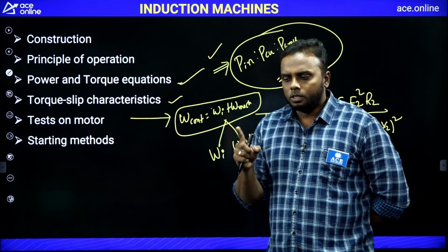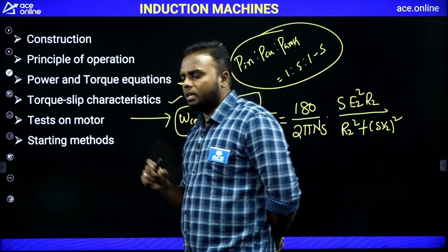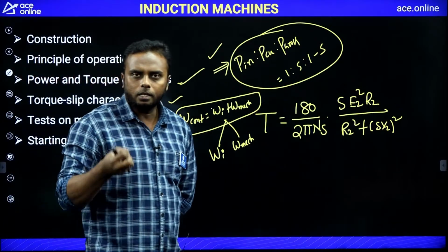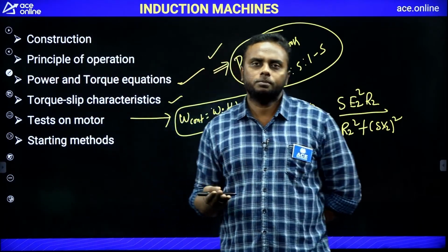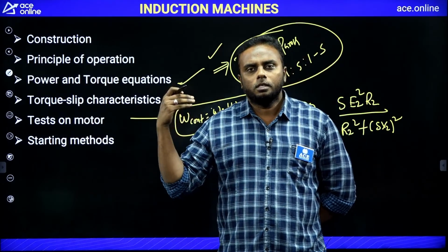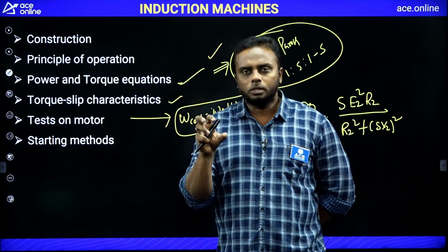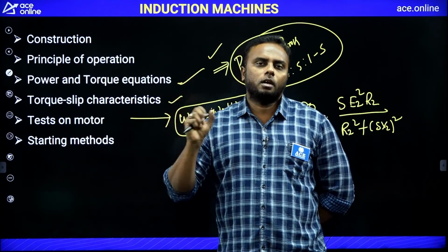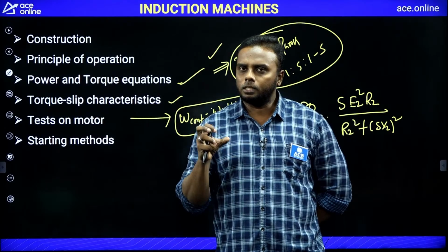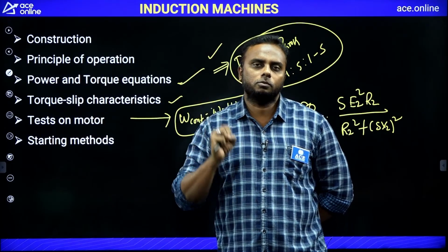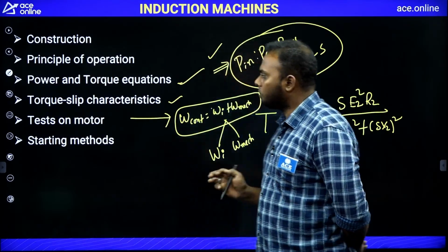So under short circuit, whenever the load resistance acts as 0 or short circuit, it will take high current. That is one reason. Another reason, with relative speed: whenever supply is given to the motor, the rotor speed is 0. At that time slip is 1, and the relative speed between the RMF and rotor winding is very high, which is synchronous speed, which causes high voltage. As the rotor winding is shorted, high currents will flow. Okay, like this we saw 2 reasons.